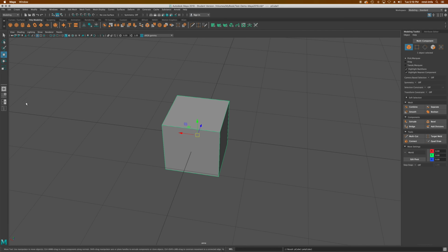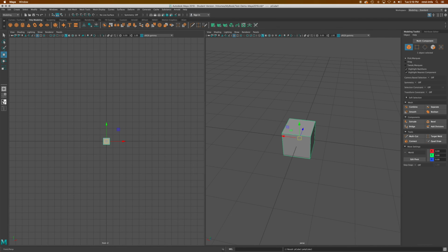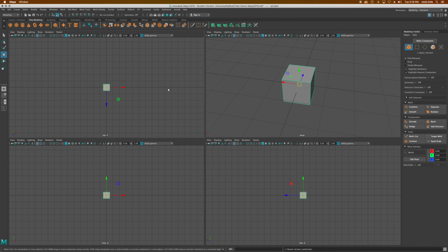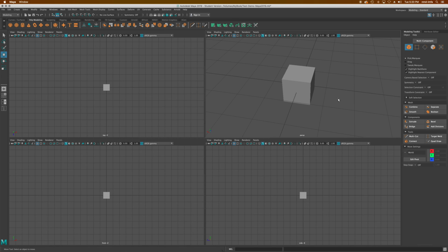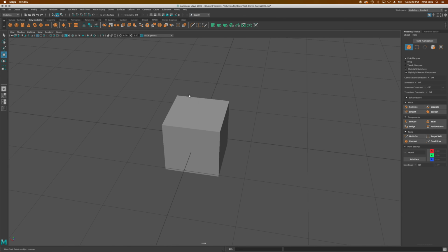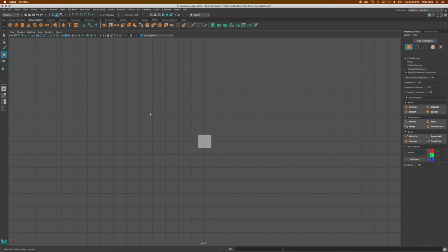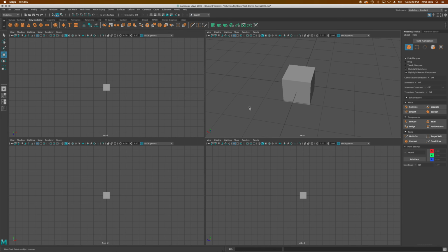And if you look over here on the left, you have a four-way view and you have a two-way view. And this is really important. And the shortcut for these is spacebar. So if I hit spacebar, I move back to that single view, or if I hit spacebar again, I get all four views. And it's going to toggle based on which viewport you've clicked in. Sometimes it's a little hard to see, but each of these viewports, when I click in them, gets a little light gray outline around them. So if I click in the perspective view and I hit spacebar, it'll just show me that one. But if I click in, say, the top view and hit spacebar, then it's going to zoom to that one instead. So keep in mind you can click through these various viewports. But I'm going to have the four-way view up here so that I can keep track of what's going on with my object as I move it in space.